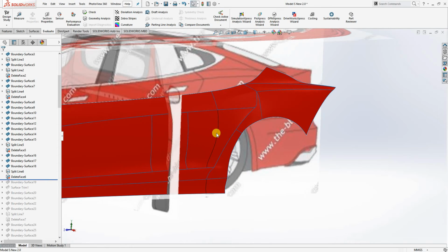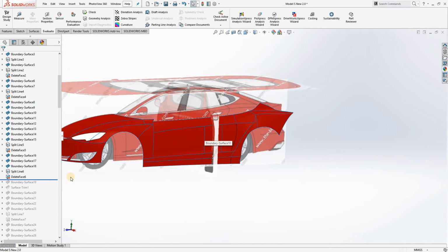I think generally if you're surface modeling simple products, they can still have organic shape, but they don't consist of too many surfaces. You can put the work in to make all the boundaries G2 continuous, but with something this big, it's not really practical.